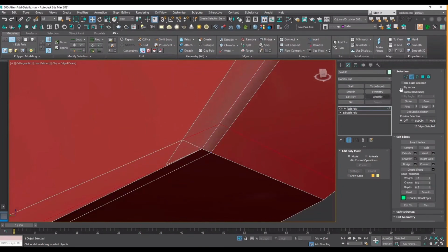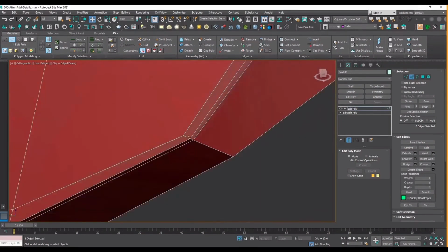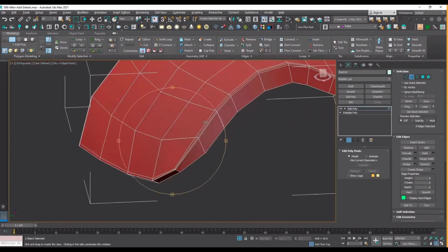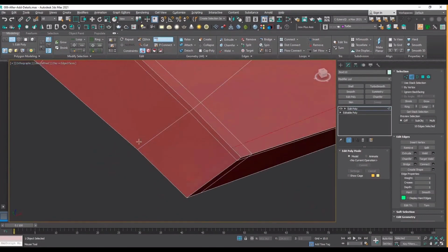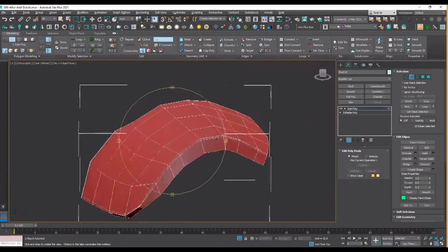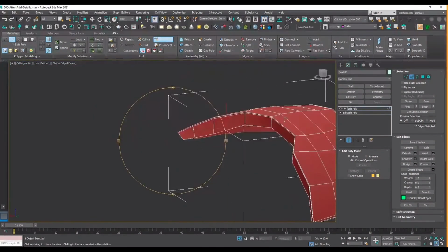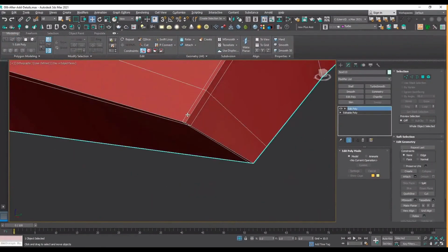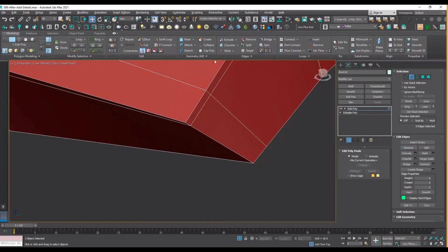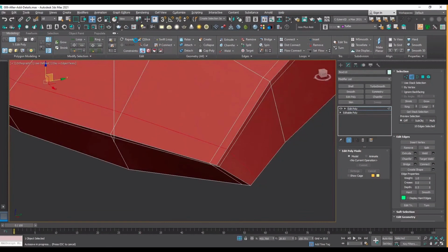And as you can see, currently I'm dealing with the same type of problem I had before. Added the edge loops, selected the unnecessary parts, connected where I had to, and now I'm just rotating and observing the different parts of the mesh to add the possible adjustments and Control Remove, and then replace the edge here.